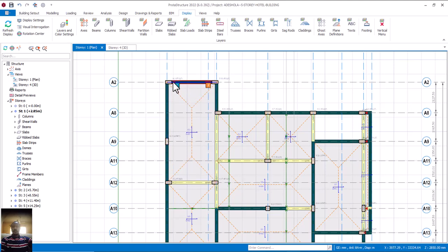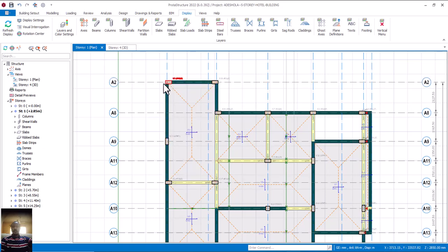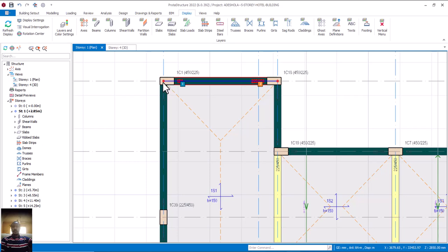So if you don't hinge it, the software will see it as a fixed end support, instead of a pin. The moment the software notices that this place is fixed, automatically it's going to provide reinforcement. Whereas even in school, you know that the moment at this point is 0. That is why in our diagram it always comes from this point like this, comes down like this, and goes like this, isn't it?